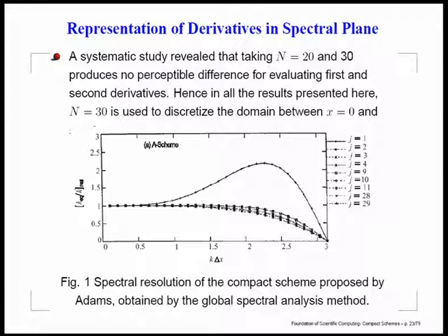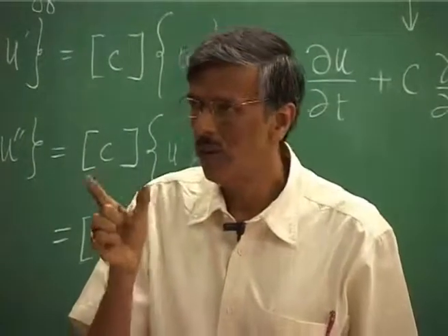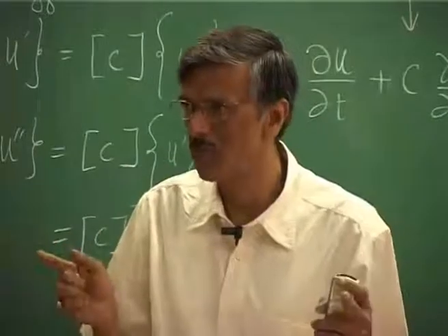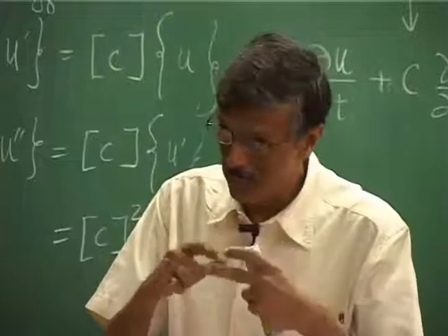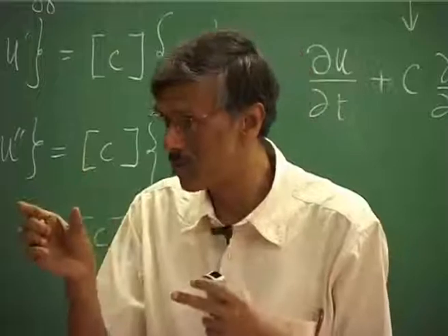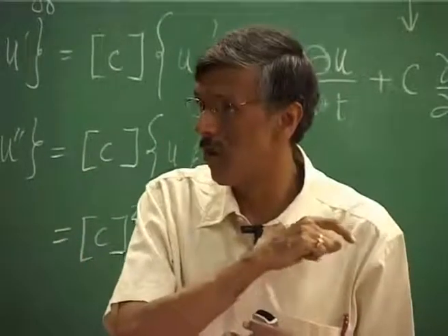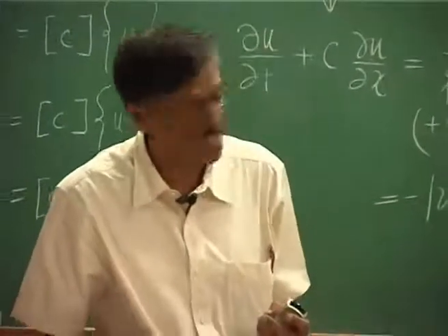Okay. I think this is instructive, because spectral methods are always used with uniform spacing. You cannot use a spectral method with non-uniform spacing, whereas this compact scheme we can use after mapping your governing equation to the transform plane, and in the transform plane you have equispaced nodes, and there you can use this. So, this makes it somewhat of a utility that we will see as we go along. Okay.